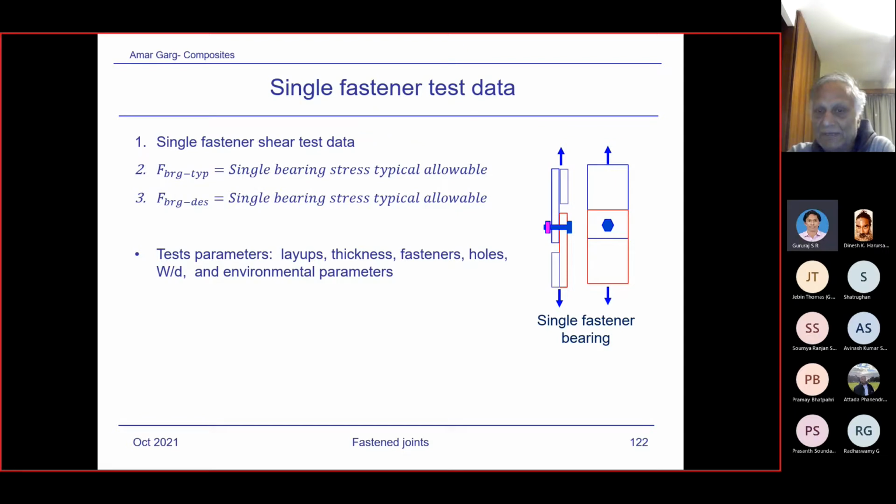And as I said at that time, with the first model which we had, before testing, when we got the test results, some of the results were out by more than 10%. So again, our engineers had to work out why there is a difference, looking into the stiffness, the ply thickness or laminate thickness, the type of the elements. And that took a lot of time.